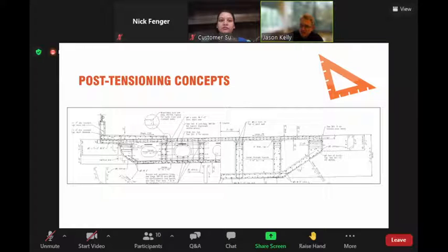And on the left is the new bridge with pre-stressed post-tensioning strand in it. It's going the same distance, but you can see on the left, it's not nearly as deep. There's not nearly as much concrete. So it's a much more efficient shape. It uses less materials. It can go farther.